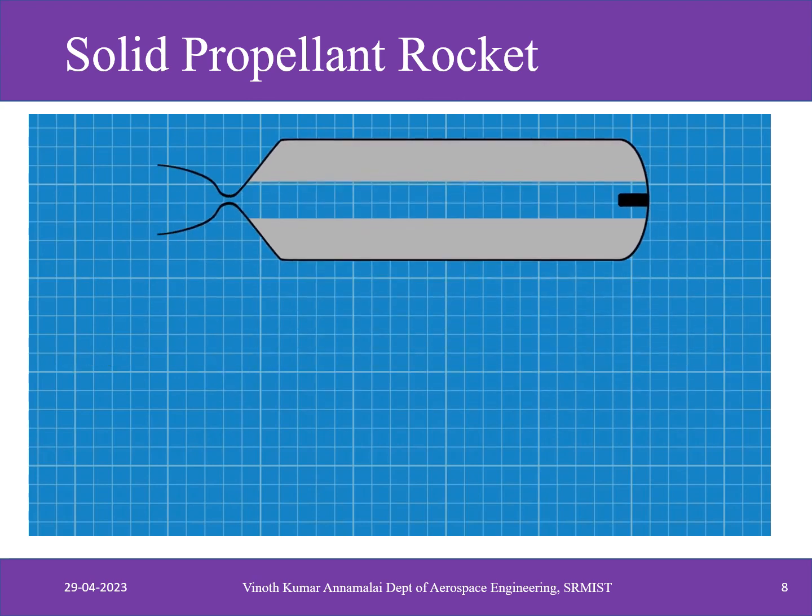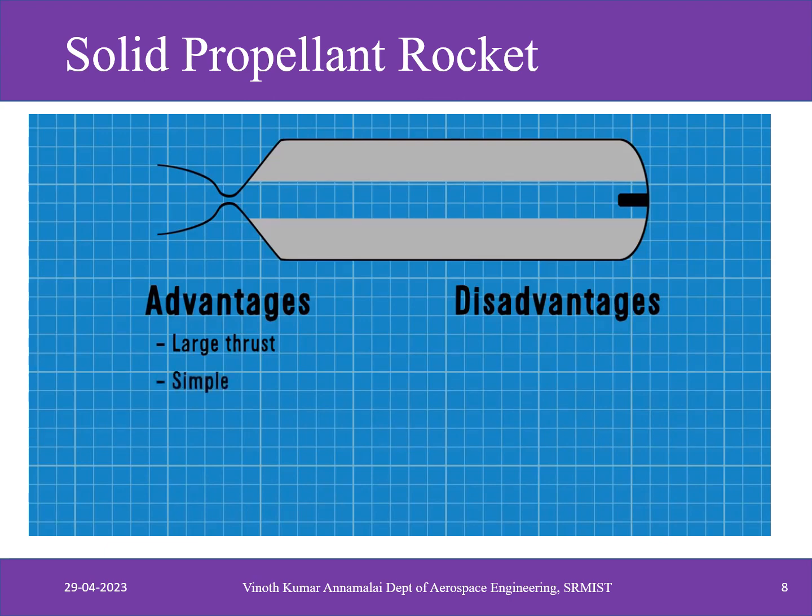Solid propulsion has a number of advantages and disadvantages. A major advantage is that it generates a larger thrust than similarly sized liquid propulsion does, albeit for a shorter period of time. It's also simpler than liquid propulsion. This makes it cheap. The thrust per cost ratio is high. The thrust can't be actively changed during flight. Once ignited, it will burn the way it was designed to burn. You can't push some button and decrease the thrust by 10%, as is the case with most liquid chemical propulsion systems.